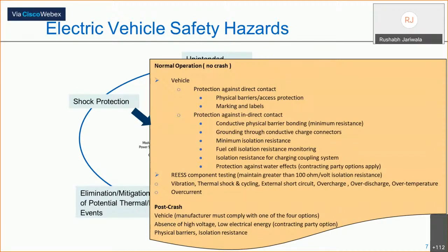Especially the compartments of the HV battery and its cells should be designed such that under normal circumstances it is absolutely not possible for a human being or service personnel to touch a live part, because the HV battery always stores a very heavy charge, and even one direct contact can take away the life of a person.